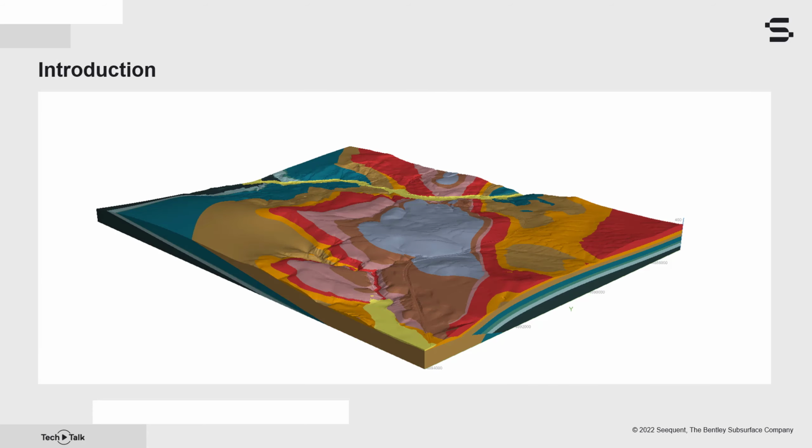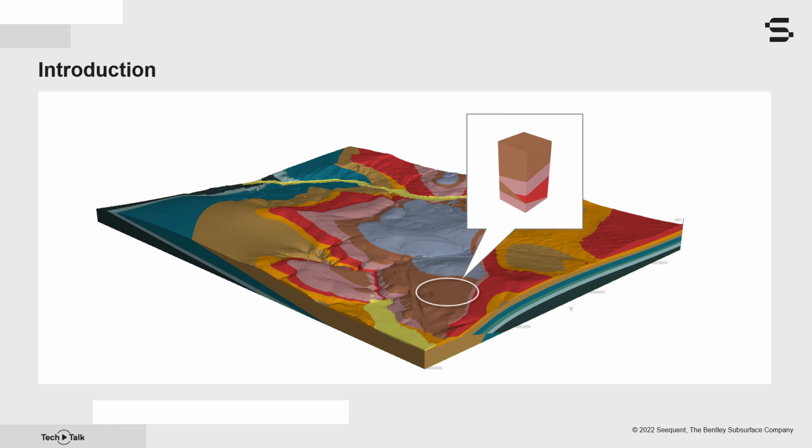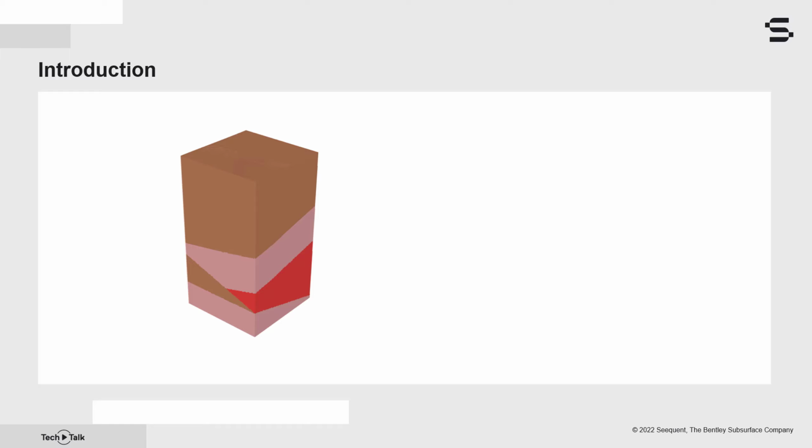Let us quickly review the project location. Here's the regional geology of our project site in central Alaska, where our building is to be constructed. In last month's Tech Talk, we created the 3D domain using a small portion of the regional geology. The top brown material in our domain represents an ice-rich silt. The top portion of this can be considered an active layer where temperatures fluctuate above and below the freezing point of pure water over the course of a year.